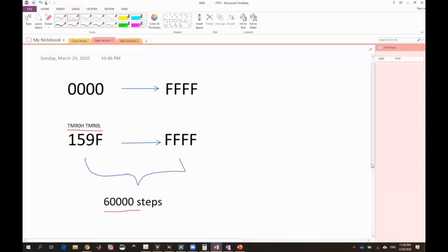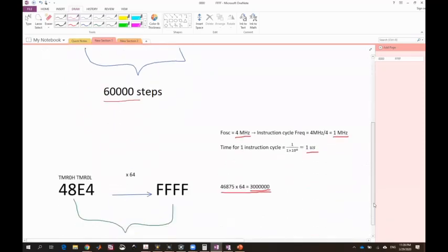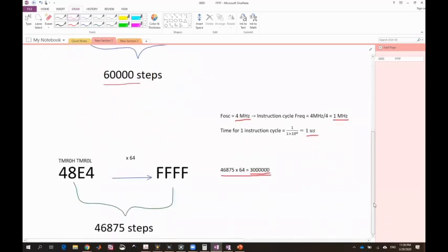And in the other example that we have seen, if we want to use a prescaler, if you want the timer to generate an interrupt after a time greater than 65 milliseconds, the example given here was for 3 seconds. So if you want the timer to generate an interrupt after 3 seconds, then we have to use a prescaler to slow down the timer.